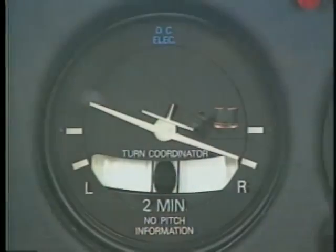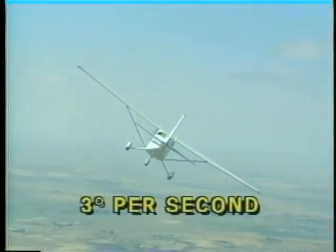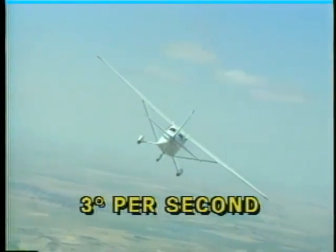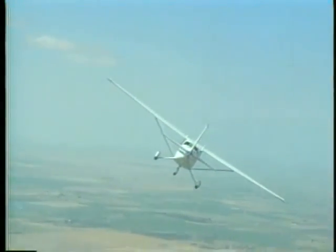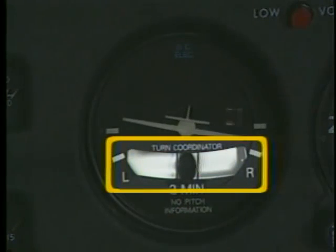With the wings of the miniature airplane aligned with the reference mark, you'll turn at a rate of 3 degrees per second. The second part of the turn coordinator is the inclinometer. Just as in VFR flight, the ball helps you maintain coordinated flight.